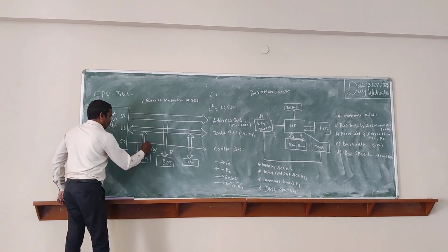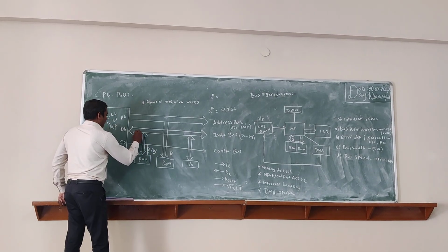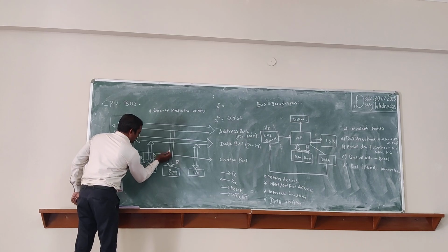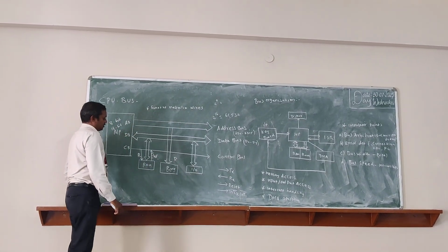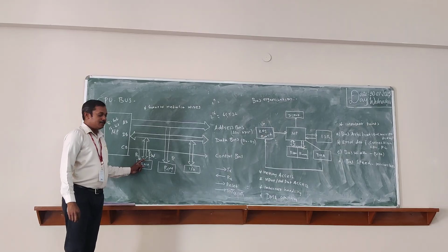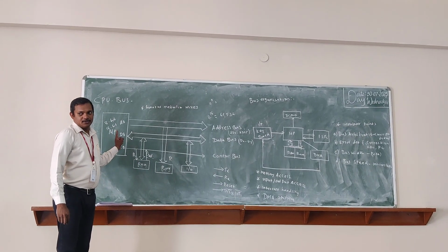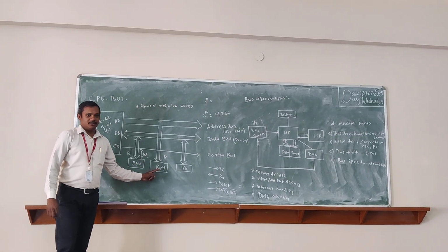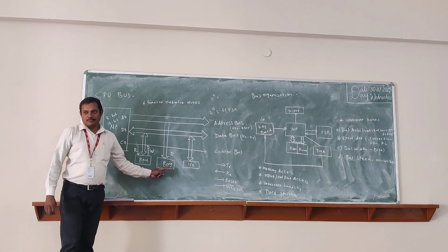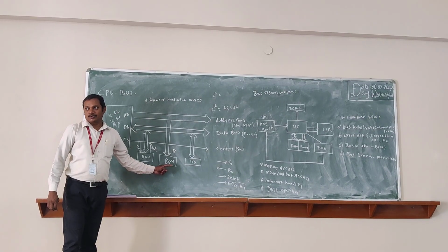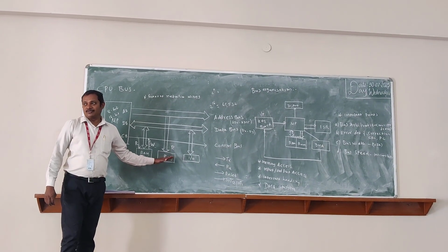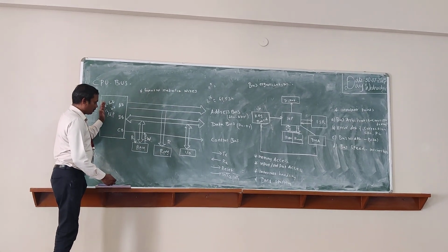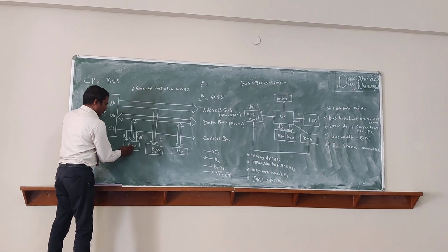So here we have an arrow, control bus. So this will be a read and this will be a write. Because this RAM acts as a mediator between ROM and microprocessor. Okay. As I emphasized earlier, RAM is a data memory, ROM is a program memory. We write the code in the ROM. Okay, it's a one-time program. All the source code will be written in ROM. That's called firmware, we call it firmware in software development. So here, between microprocessor and ROM, this acts as a mediator.